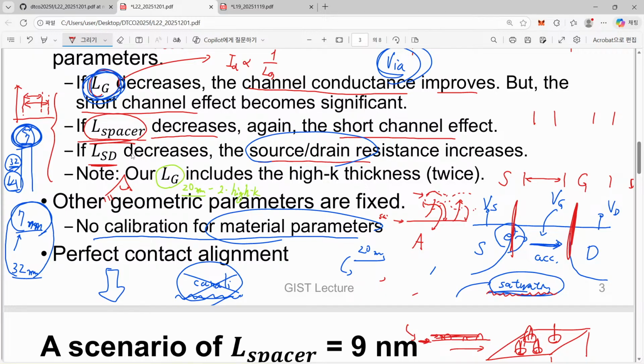So that's the reason why we have a velocity saturation. Now you understand, in order to keep this trend, we have to have sufficient length and time to have the scattering event, and sufficient chances are required. However, this is so short. So therefore, speeding electrons can arrive at the drain even without being caught by scatterers. So let me just give you another analogy.